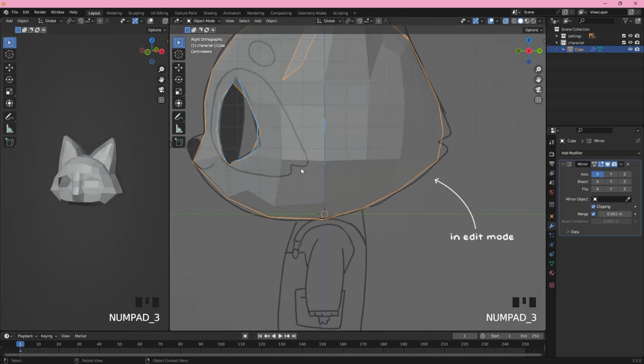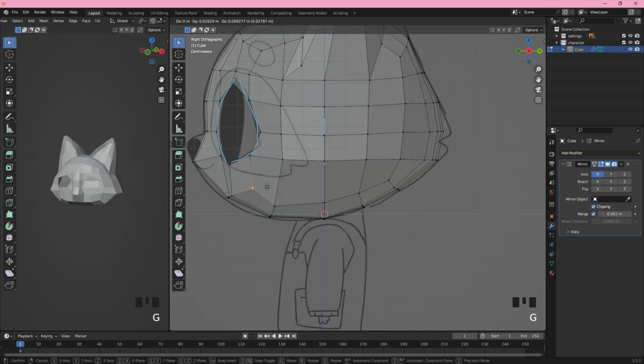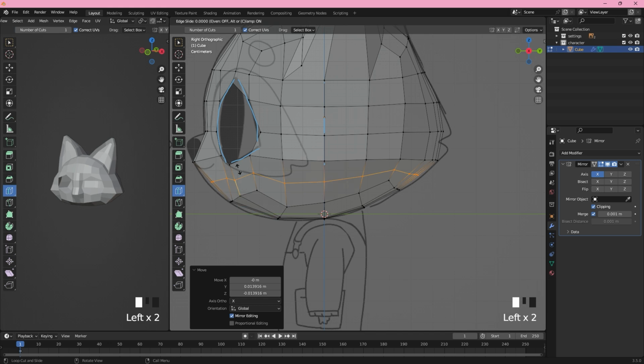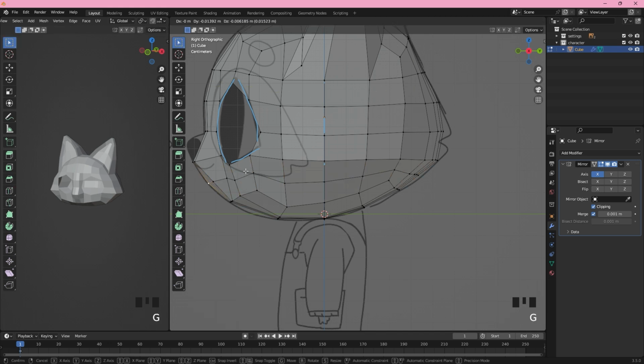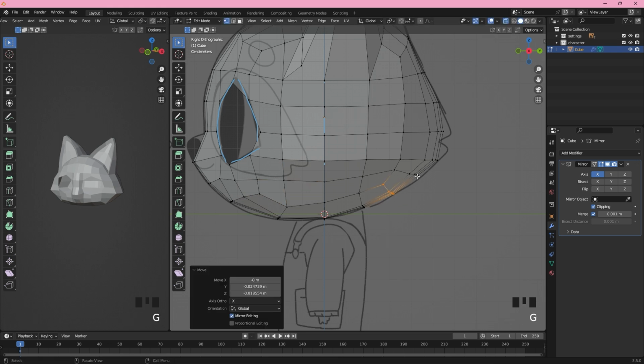Let's move back to the face from the side view. I'm moving a bit these vertices to make some space because we're going to add another loop. Here just below the eyes, let's add a new loop and then move a bit the vertices around just to rearrange them. I can't really tell you where to place them specifically because we just want to try to space them equally, just like so. There is no rush, so take time to watch your head from different points of view just to make sure we don't have any harsh edges or weird vertices that could make the face weird.